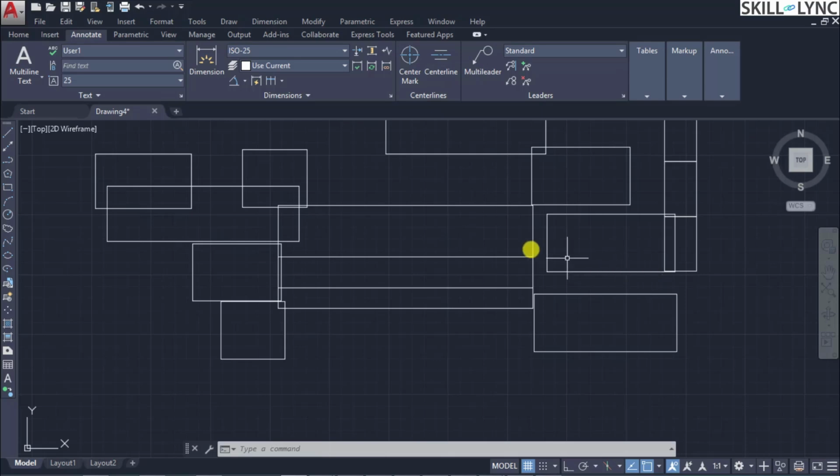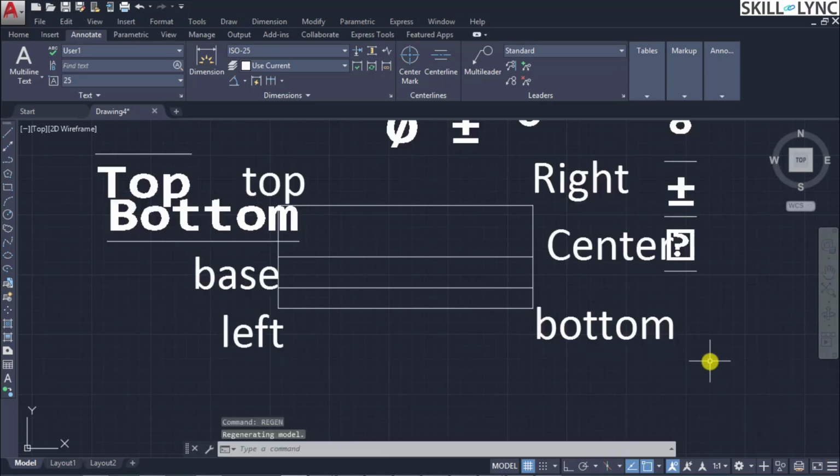It means that you are slicing this entire drawing into different layers. Suppose all the text is assigned to a single layer whereas the drawing is assigned to another layer, then the layer of text can be hidden completely so that you can operate only on the drawing layer. Okay, so now to enable back the text, you have to disable the qtext command again and then type in regen so as to have the view back.